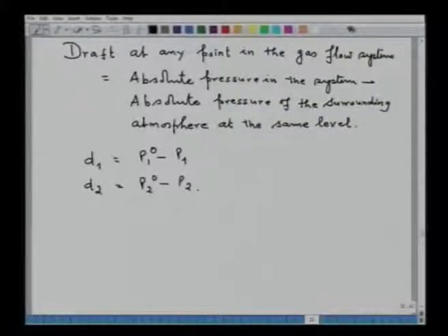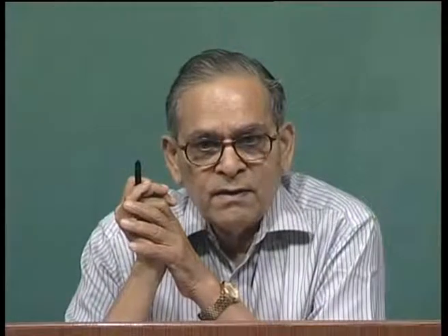Now, it is also important, since small pressure differences are controlling factors in the furnace system, so variation of pressure with height in a gas column is important. If you consider a gas column of certain height, then accordingly the pressure exerted on a particular point will be influenced by the height. So it is also important to consider the variation of pressure with the decrease in height.